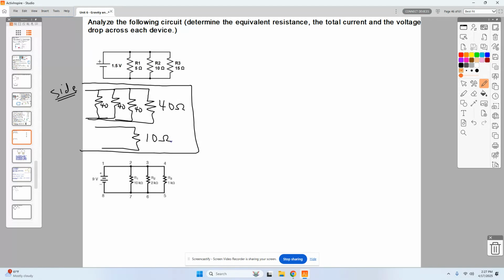What if I had 3 resistors and they were all 60 ohms? So again, this is an aside, so that we don't have to do a lot of fancy math here. If they're all 60 and I have 3 of them connected together, the equivalent would be how much? Divide that in thirds, right? So 60 divided by 3 would be 20. That would be an equivalent resistance of 20 ohms.